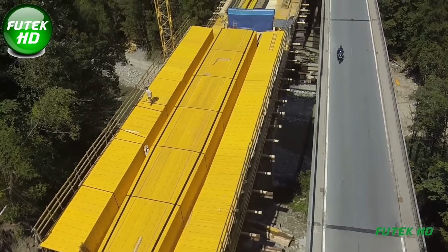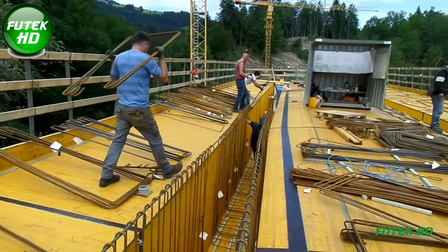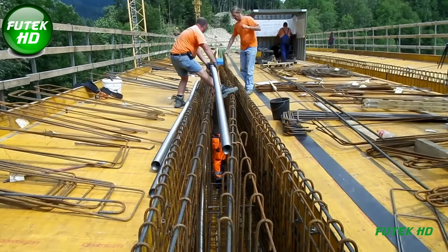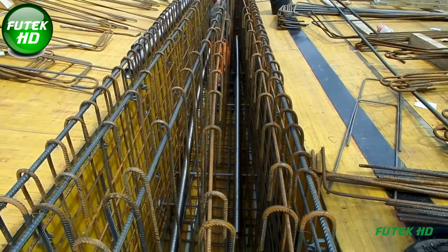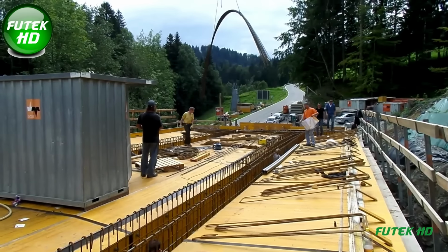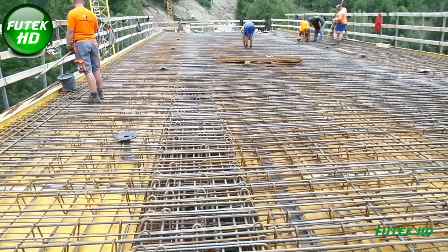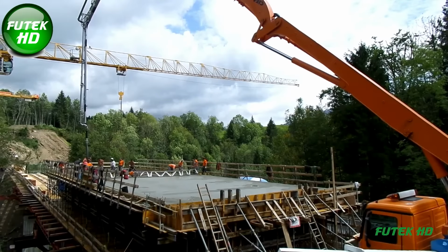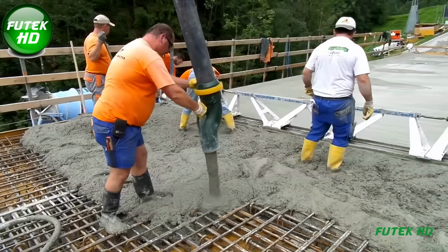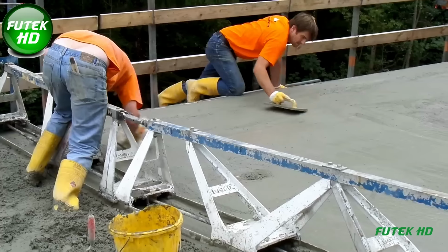During the winter months, construction continued to progress on the piers to maintain the ambitious timeline, and by the end of February 2014, the foundation work was completed. The foundation for the piers was achieved through the use of deep wells up to 9 meters, constructed using the shotcrete method. Additionally, permanent anchors up to 29 meters long were installed to manage the horizontal loads at the abutments. Despite unfavorable subsoil properties, the project overcame these difficulties through deep foundations achieved with drilled micro-piles.